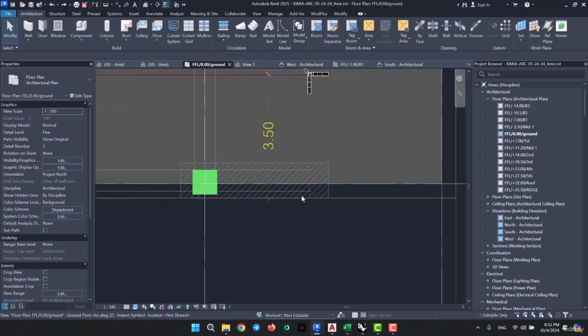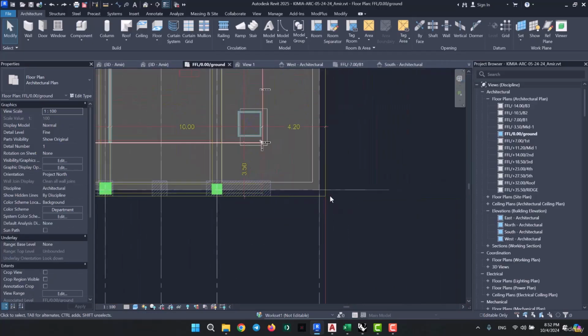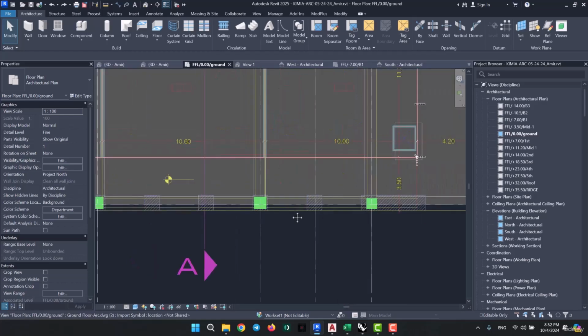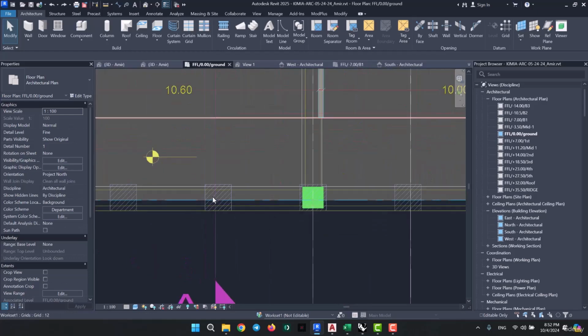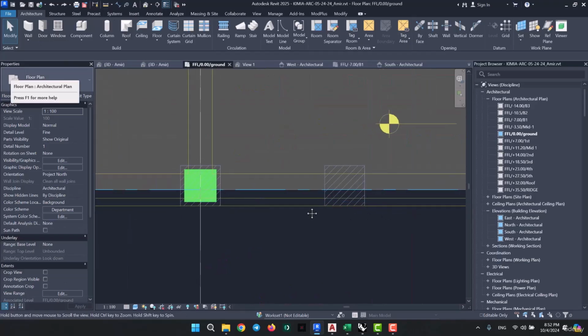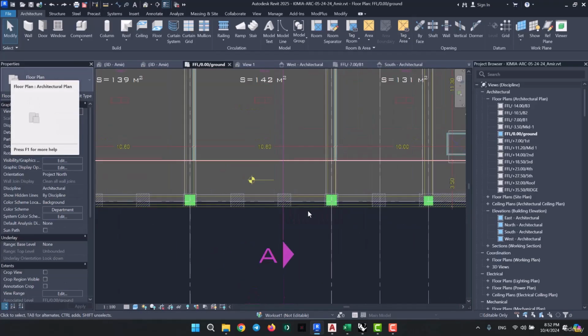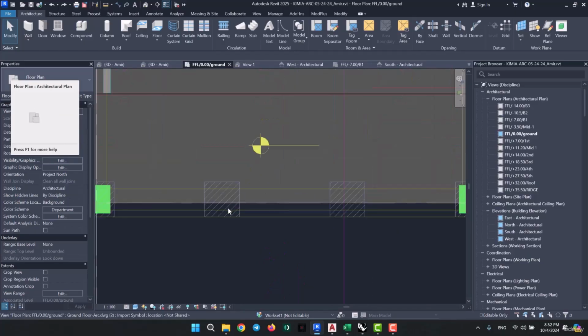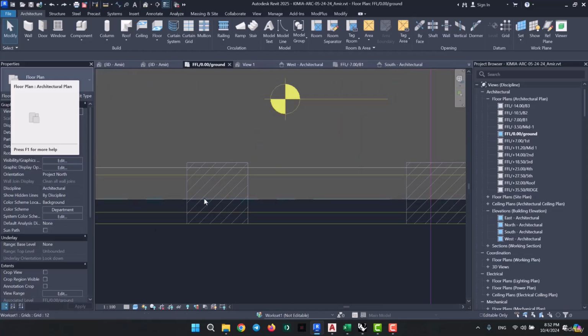If you go take a look over here at the ground floor, we might get a little bit confused as to how we can draw the wall all around here in one single piece. The way that these walls are designed is that we're going to need to form some squares, as in one here and another here. How can we even do this all around the building? For modeling such walls, there is a solution, which is that you could go onto one of these design squares and make those false walls into wall layers. So then for the inside part, you could just add an insulation layer. Basically, you would be making a multi-layer wall with a wall exterior, but filled with insulation.